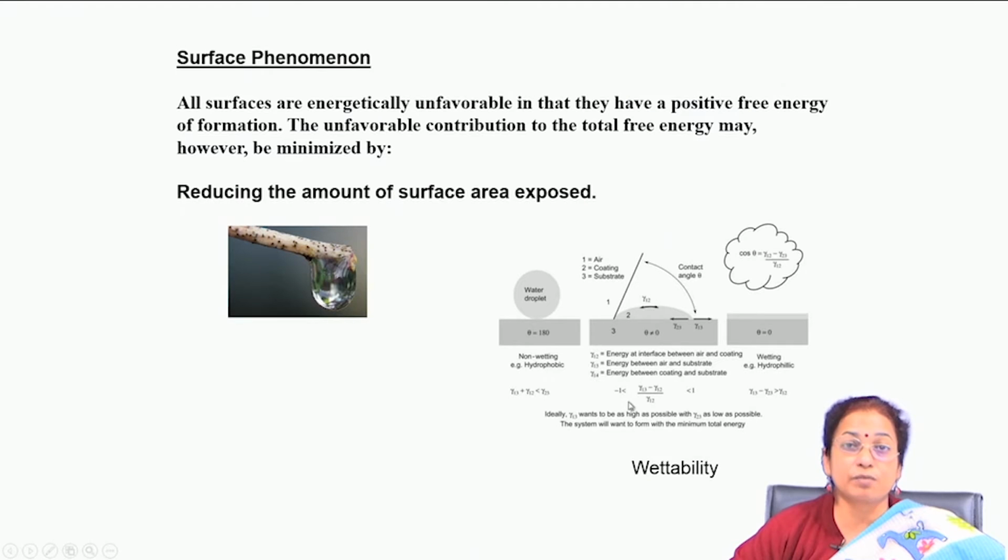Another very important property of the material, again driven by surface energy, is wettability. Depending on the surface energy, the wetting behavior will vary. Wettability is measured in terms of the contact angle. When a liquid is poured on the surface of a solid, it may spread, or it may retain the shape of a sphere. When the contact angle is quite high, it is called a hydrophobic surface. When it is very low, it is called a hydrophilic surface, and all of this is driven by surface energy or interfacial energy.